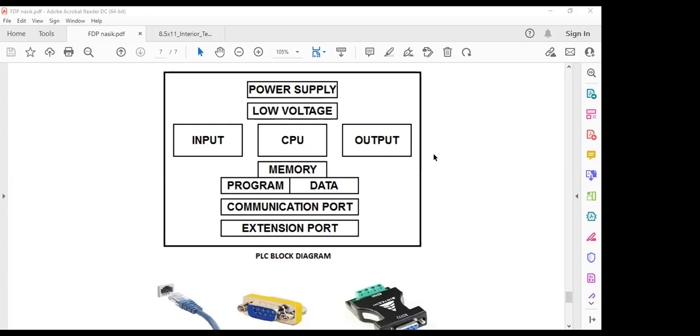But encoder, correct? We have different types of control encoder. Encoder is the device we use for taking feedback of the motor. That encoder will be a disk kind of structure. This is put on the rotating part, and that encoder will generate a number of pulses. Pulses means on-off signal, high frequency on-off signal.